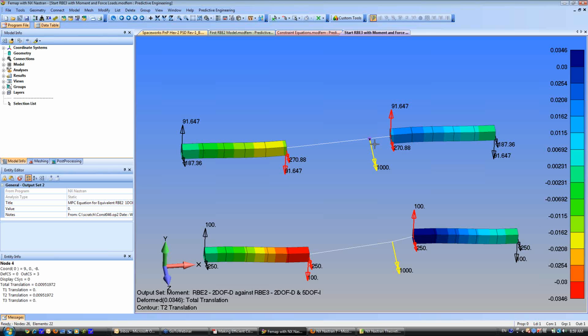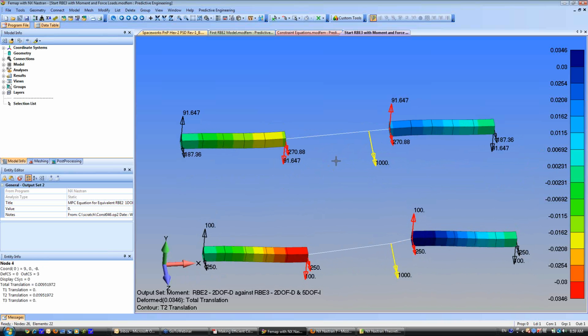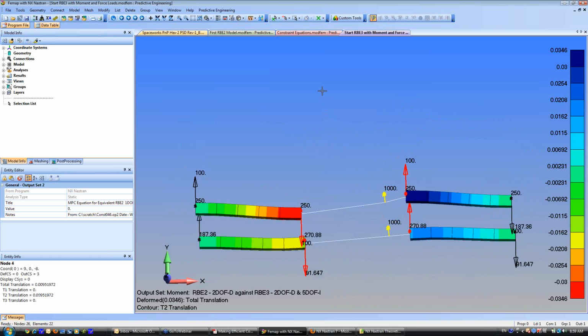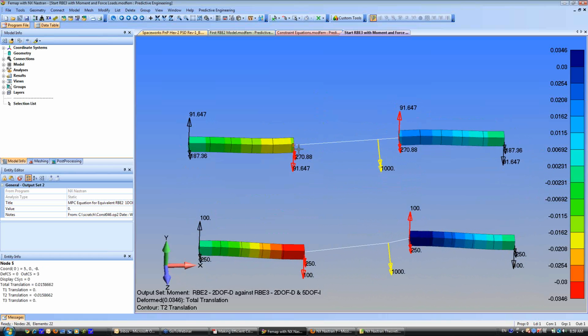Rigid links transfer stiffness. And since we've tied the y degree of freedom and the RZ degree of freedom together, we've said this is an infinitely stiff constraint. It's being applied via constraints, so it's going to be infinitely stiff. And we're saying this bar here, we're giving 1,000 units of torque. So this bar is just twisting.